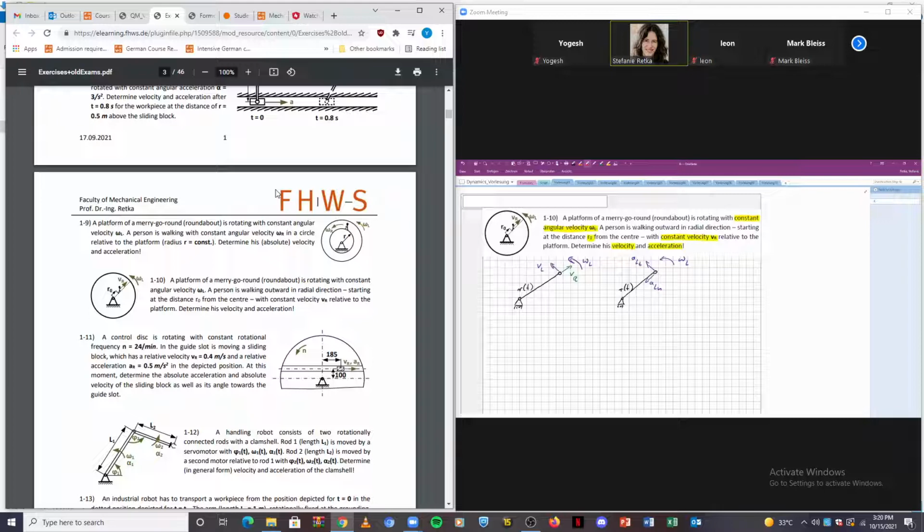So again, the thumb corresponds to the axis of rotation of the leading velocity, the index finger points in direction of the relative velocity, and our middle finger indicates the direction of Coriolis acceleration, pointing that way.